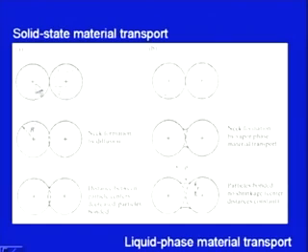When these two metal particles come close to each other, there is a neck formation by diffusion. The diffusion process takes place where the two metal particles meet, the distance between the particle centers decreases, and the particles get bonded.